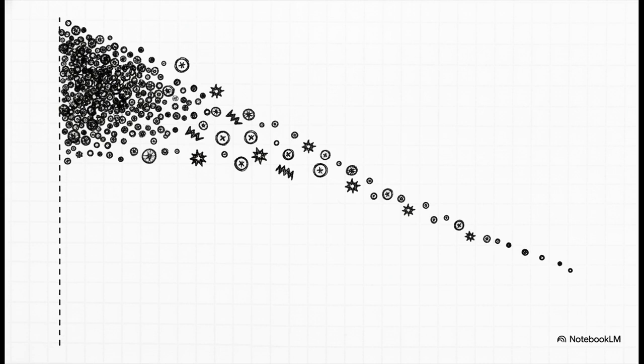A diode is the absolute fundamental building block of electronics. It lets current flow in one direction, but perfectly blocks it in the other. When you apply a forward voltage, you lower the diode's internal barrier. Suddenly, minority carriers just flood across the junction. But because of that survival dynamic we just looked at, their numbers naturally dwindle the further they travel into the material. This creates this beautifully steep exponential decay profile.